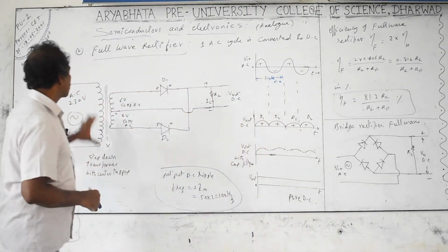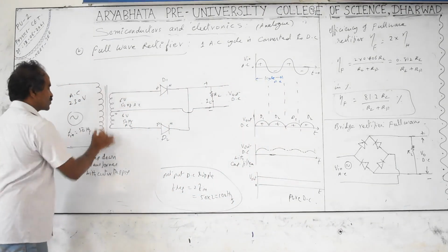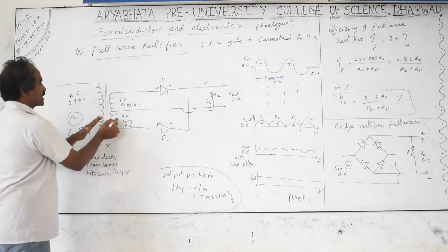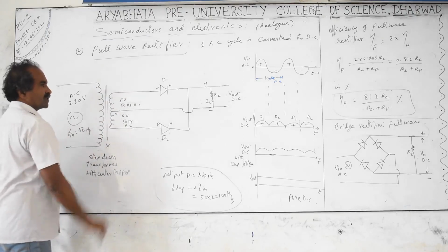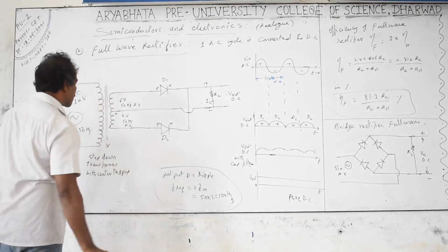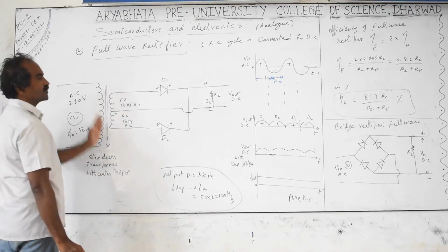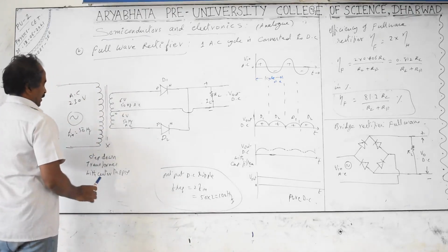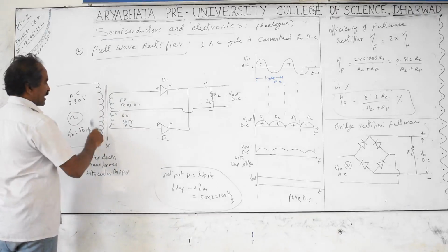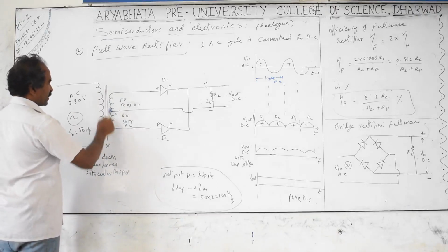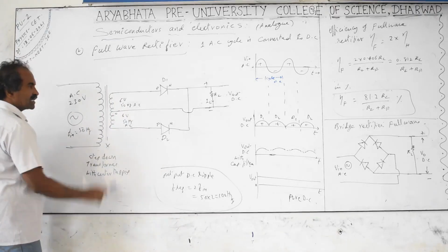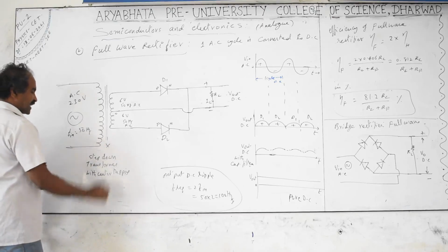In this, we have the step down transformer. These center lines, these two lines between the primary coil and secondary coil, indicate the core, a soft ferrite core or laminated core, which we use to reduce the eddy currents and to increase the magnetic flux linkage between the primary and secondary coils. The transformer symbol in circuit diagrams is generally taken as X.